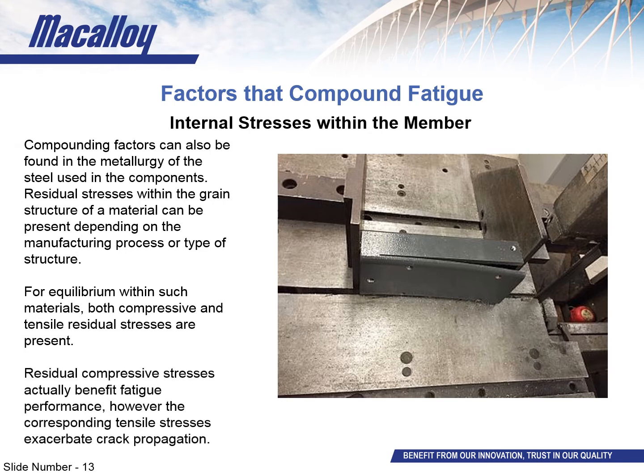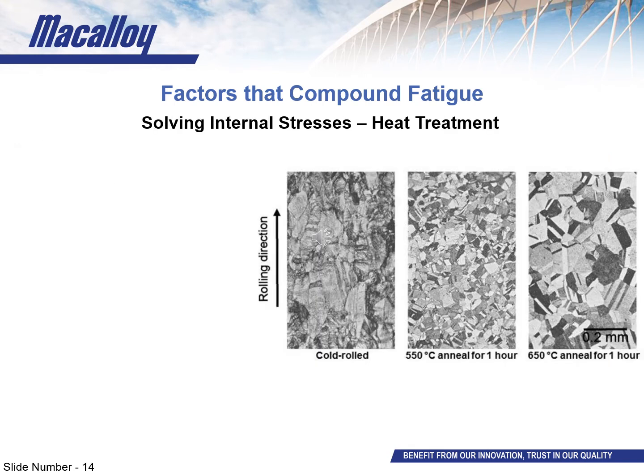Now, thinking about how fatigue damages a material, it's cracks that grow throughout the steel. So, compressive forces in the steel matrix, forcing the grains together, actually do improve its fatigue resistance. But no yin is without its yang, and the tensile stresses that go with these compressive stresses exacerbate the growth of cracks. And as it only takes one significant crack for a fatigue failure to occur, residual tensile stresses are an absolute no-no. As a result, for a fatigue system, these stresses need to be removed. This is in order to minimize the likelihood of any crack forming and propagating in the steel.